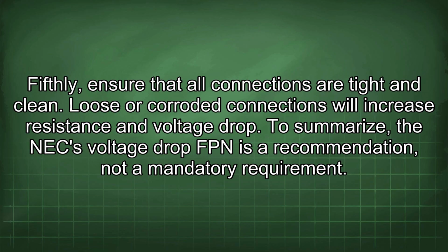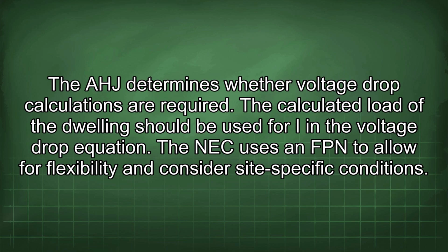To summarize, the NEC voltage drop FPN is a recommendation, not a mandatory requirement. The AHJ determines whether voltage drop calculations are required. The calculated load of the dwelling should be used in the voltage drop equation. The NEC uses an FPN to allow for flexibility and consider site-specific conditions.